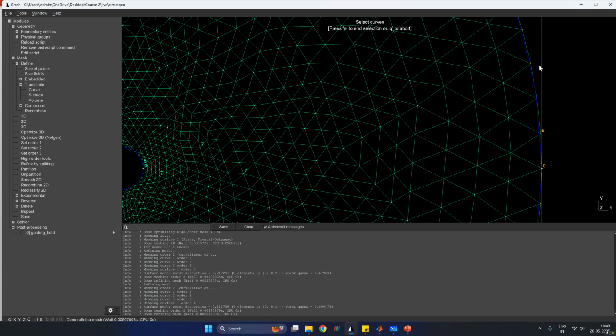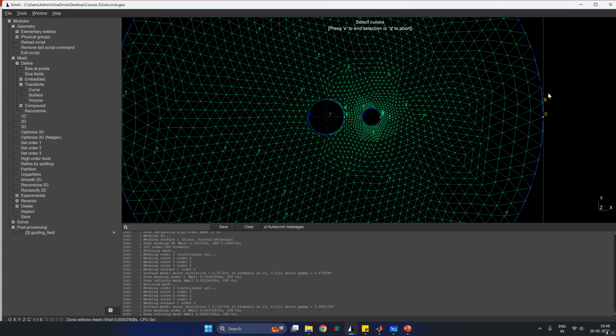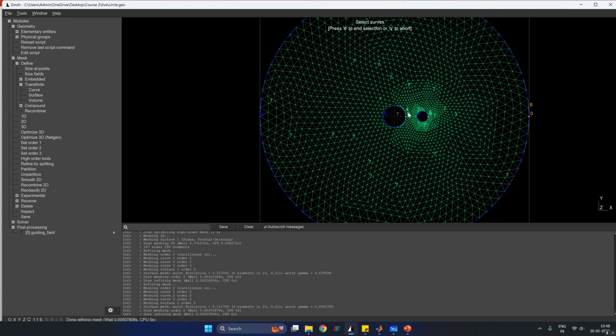When you exclude the boundary flag, and it's an internal boundary, this will act more like a flux continuity. It will do the same thing as before, that is the stiffness matrix, and naturally you always have the force vector equal to 0, because that is how you initialize. Unless you have an internal source, in that case of course the force vector will have some values. So that's about the boundary conditions, and we'll be using simple linear meshes.